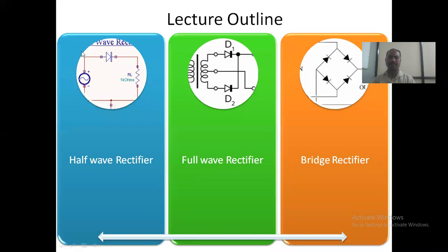This happens in the case of your half wave rectifier. That's why the output coming from a half wave rectifier is less. If we apply 10 cycles, 10 cycles indicate positive as well as negative half cycles. Only 5 positive half cycles contribute, which means the output coming should be 50%, right? This is with respect to the half wave rectifier.